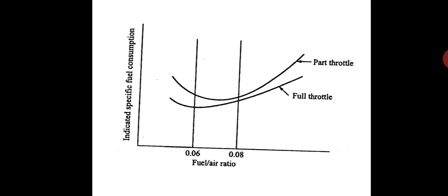The maximum indicated thermal efficiency occurs at a fuel air ratio of about 0.06 for gasoline, which is slightly leaner than the chemically correct fuel air ratio, because for the combustion excess air can be provided for this particular leaner ratio. A lean mixture lowers the maximum temperature, which favors the chemical equilibrium and specific heat of gases.